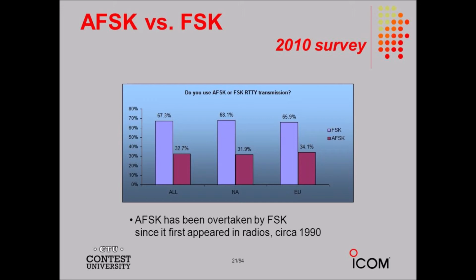Okay, turning over to page 436. Got a diagram here that says 25.5, a balanced modulator using two NPN bipolar transistors. We connect the bases in push-pull and the collectors in parallel.